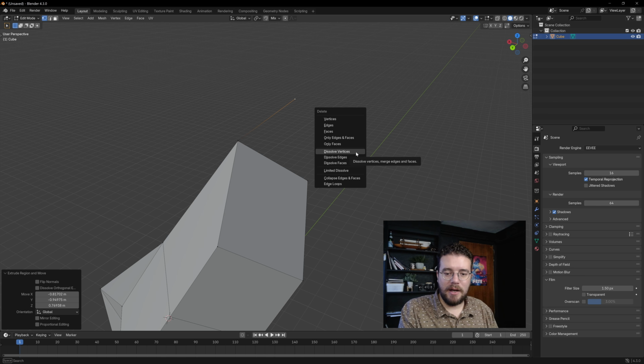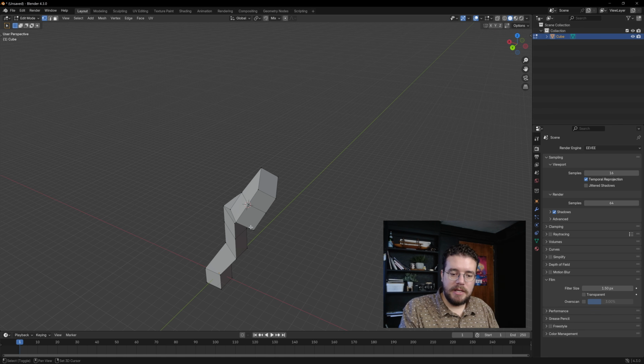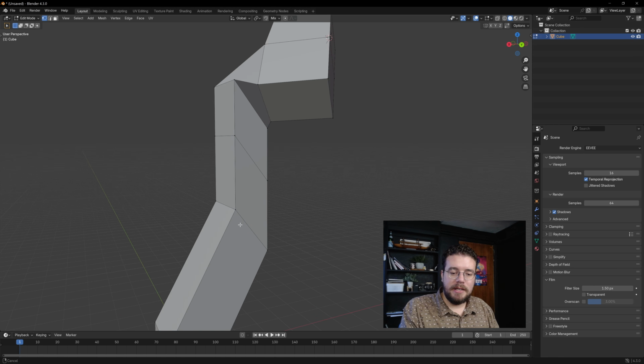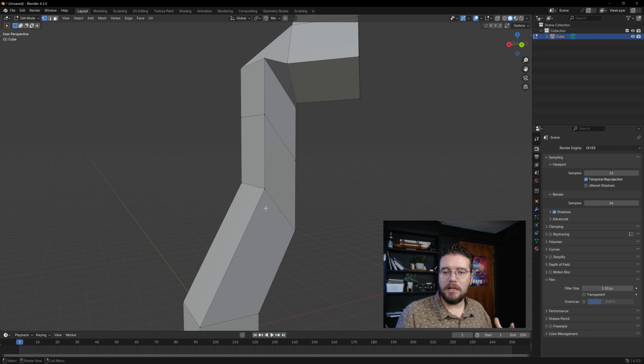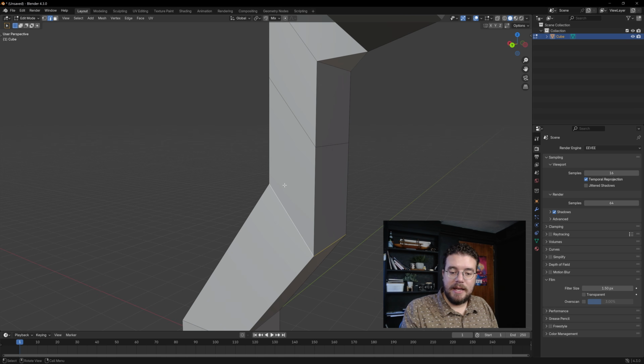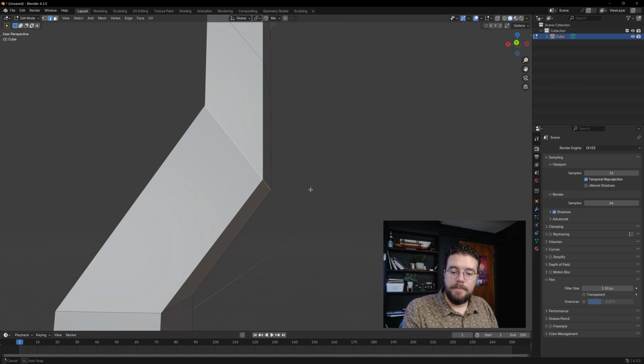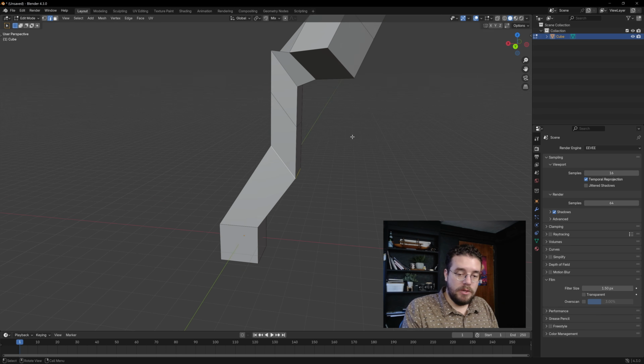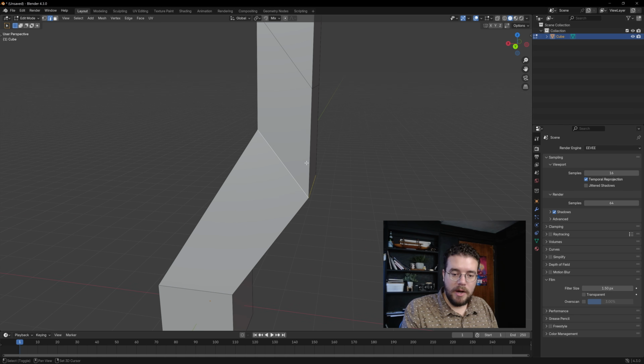So what are we talking about here? Let's delete that vertex and let me start talking about something called a loop to explain a little more about deleting. So go to edge mode with 2. As you model, we model with these components and they build up faces and they also build up what are called edge loops. To select an edge loop, just hold down Alt and click on one of these edges down at the base here. And what it's done is select a whole loop of edges. We can grab that, we can delete it, we can do whatever we want.